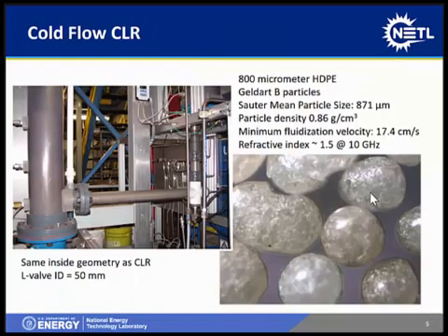Now, I am not going to talk about measurements which are done in that combustion reactor. I'm going to talk about measurements which are done in what is called a cold flow system. That is a system that operates at room temperature and is intended mostly to study the aspects of the flow environment itself. So since we're talking about measurements which are at room temperature, we don't need to use particles that are stable at high temperature. What we use instead are high-density polyethylene particles which look like this. By the way, the geometry on the inside of the cold flow reactor is exactly the same as the geometry of the combustion reactor.